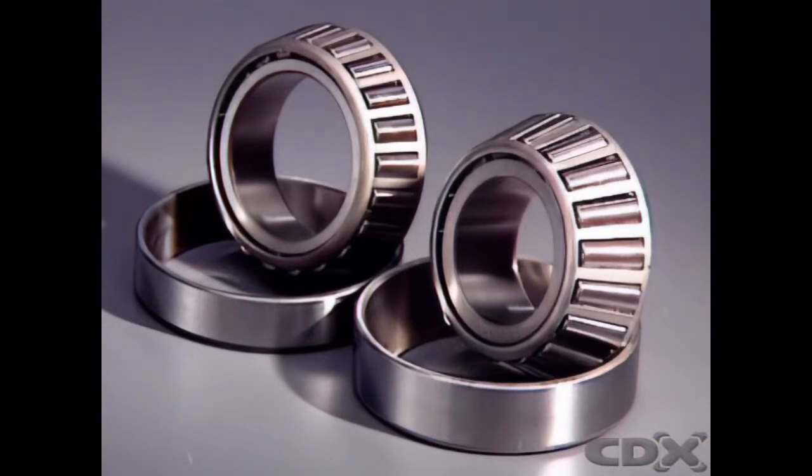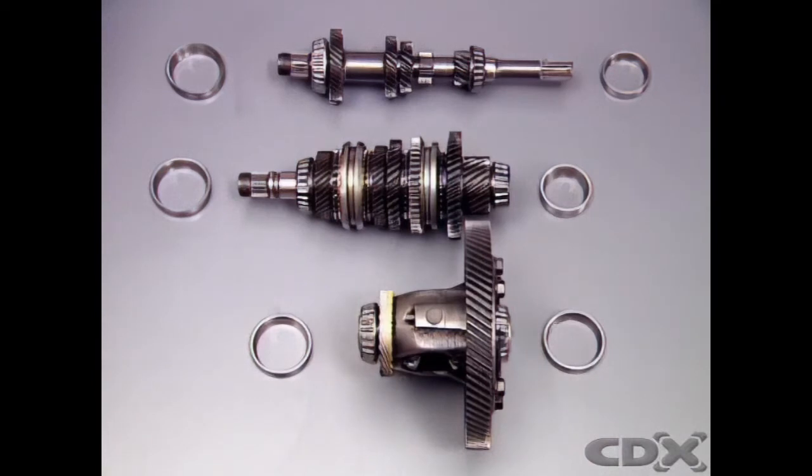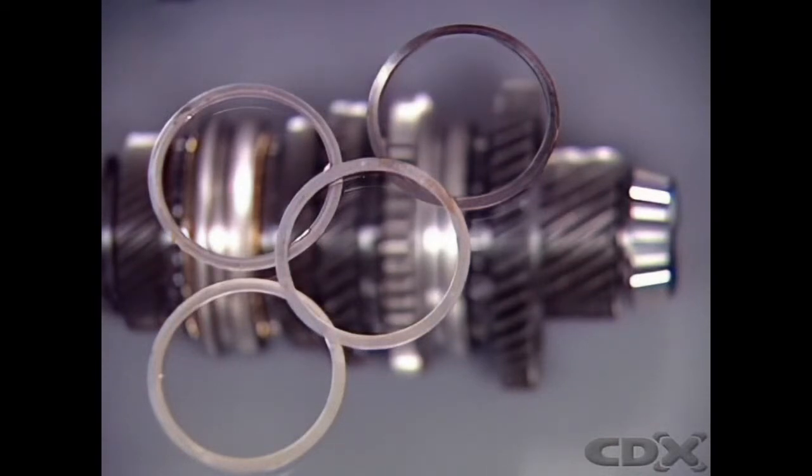Taper roller bearings are normally used in pairs and can sustain heavy radial and thrust loads in either direction. They are commonly used in transaxles, where they support the front and rear of the primary and secondary shafts and the final drive assembly. Shims or selective washers can be used to provide for adjustment of preload.